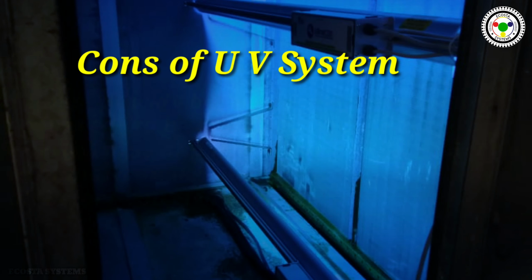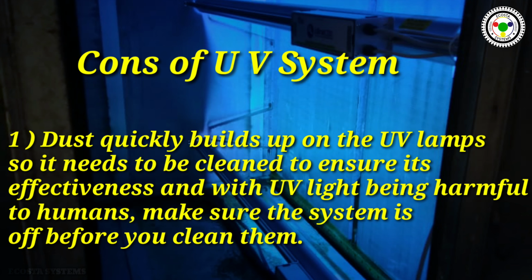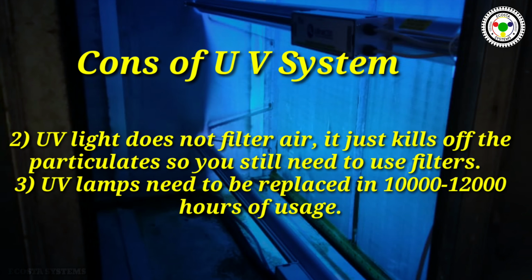Cons of the UV system. 1. Dust quickly builds up on the UV bulb, so it needs to be cleaned to ensure its effectiveness, and with UV light being harmful to humans, make sure the system is off before you clean them. 2. UV light does not filter air. It just kills off the particulates, so you still need to use filters. 3. UV lamps need to be replaced in 10,000 to 12,000 hours of usage.